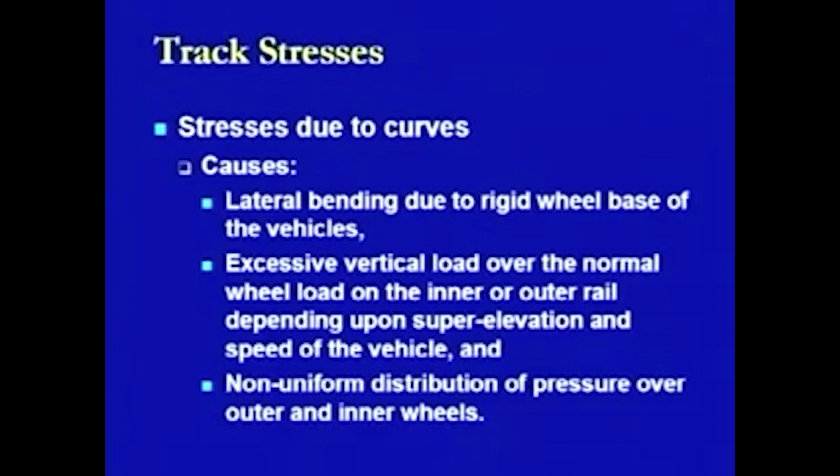Because of this rigidity of the wheelbase, the front or leading wheels and the trailing wheels do not follow the same path, so there is going to be a certain stressed condition. Similar is the case when super elevation is provided to counteract the centrifugal force. If the super elevation provided is not sufficient to counteract the centrifugal force, then also certain stresses will be induced.